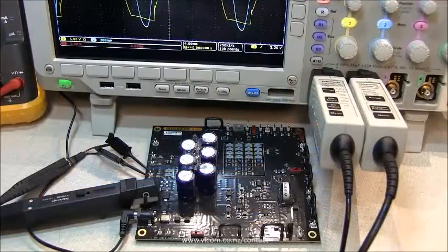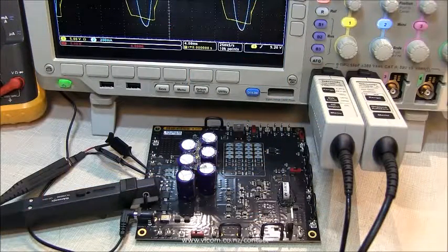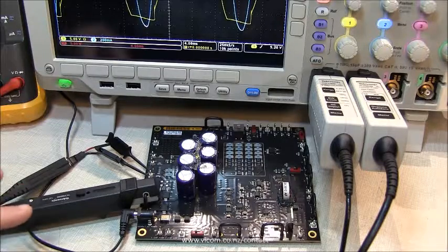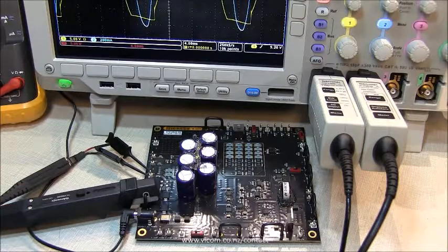harmonics. Measurements made in power systems are often non-ground referenced, or they're floating measurements, such as measuring the voltage across two terminals of a device or measuring the current through that device. This often necessitates the need for using differential probes and current probes. Now, there are a couple of procedures when using these probes that are very important to ensure accurate measurements.